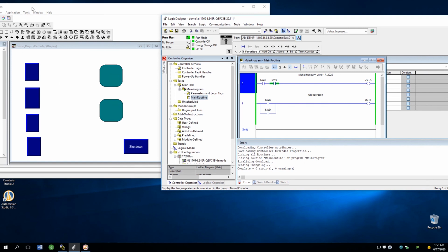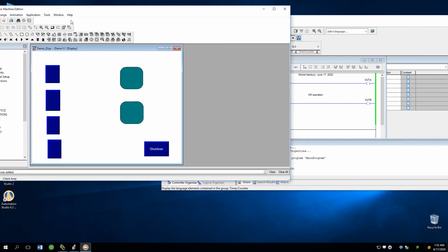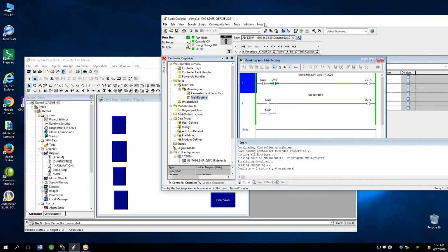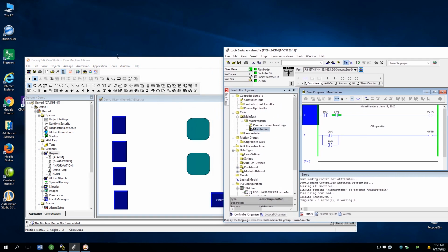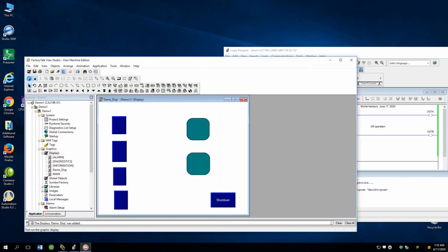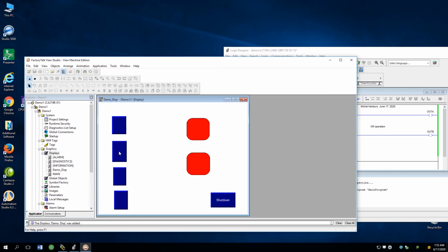And now we have to run the HMI. And again, we'll eventually get it. Okay, I think that'll do. So the HMI is stopped right now. This is the run button. So click on that button, highlight this again, and switch B is already closed, but it's hard to tell because there's no indication here, but you can change it. There's ways of changing that.